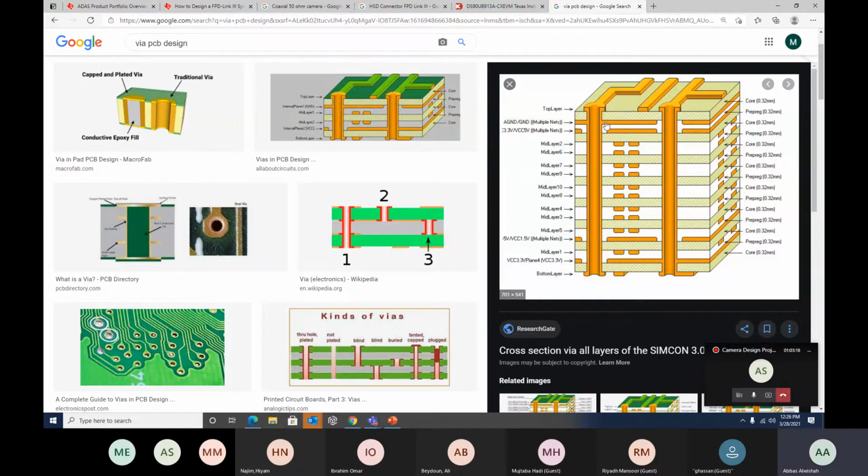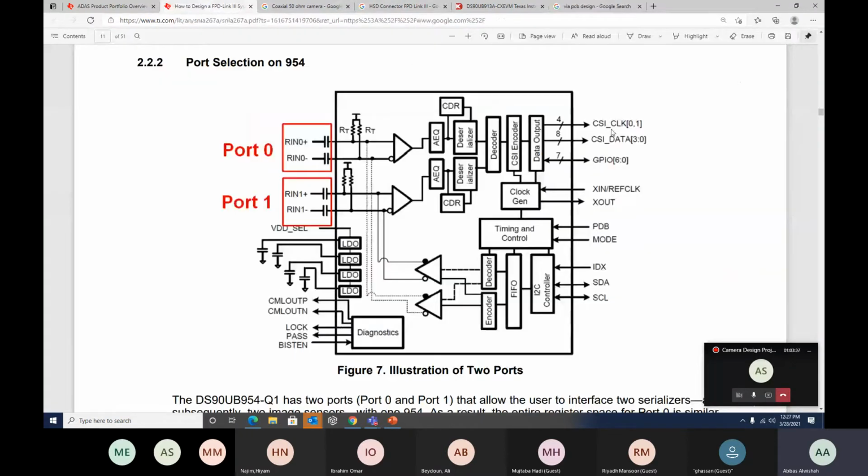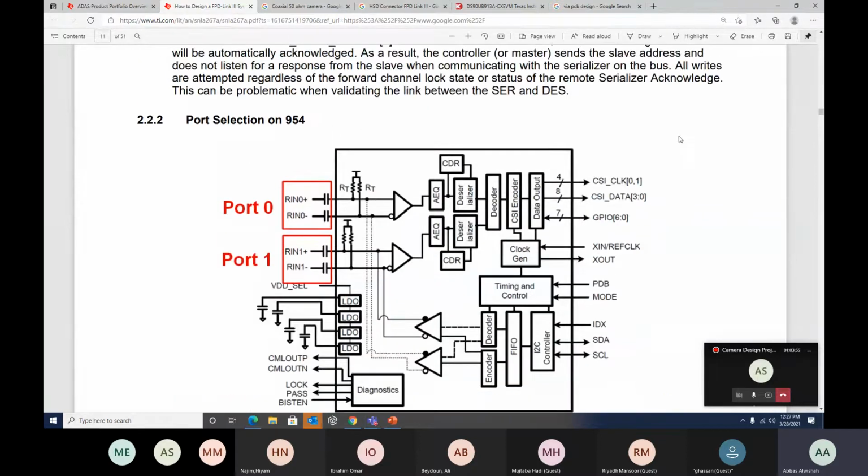So there's a via that connects, like this trace is going right to the source. And there's a via here that doesn't interfere with the rest of the traces, right? You want to set it up in a way where it's not shorting the rest of the circuits, in a way that you can tap here and look at it. Okay, I got the right value. I got the right voltage, right resistance. Okay, my issue isn't here. My issue could be with my output from here.